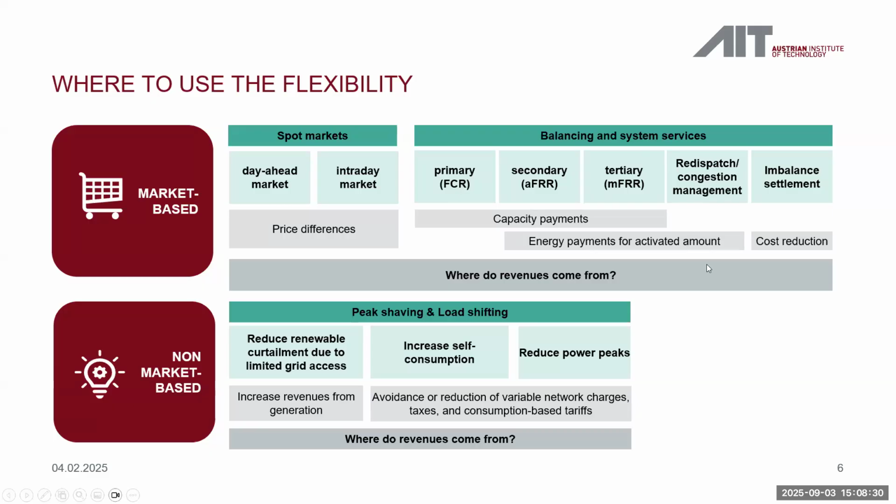And then there are also non-market-based use cases, such as peak shaving, for instance if the grid access is limited, or just to increase self-consumption or reduce power peaks. There the revenue streams come from reduced grid charges, for instance. So there are a lot of different possibilities to apply flexibility, so it's going to be very important, especially in the future.